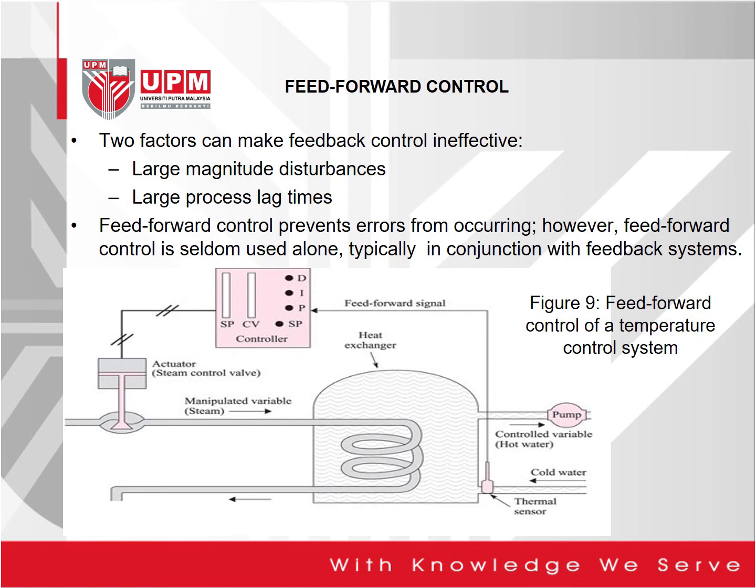Feed-forward control prevents errors from occurring. However, feed-forward control is seldom used alone, typically it is used in conjunction with a feedback system. For real applications, we do not implement the feed-forward signal alone without the feedback signal.